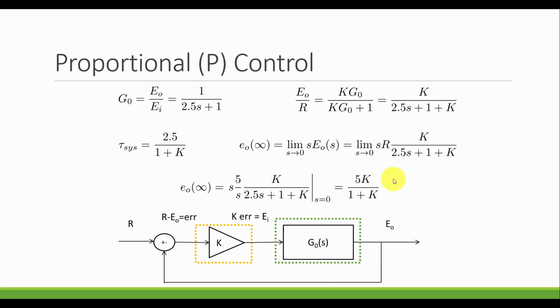I can get close, or I can get closer and closer, but it's going to require a higher and higher gain to do so. In general, when we see a steady state value like this with a K with gains in it, that's probably not a good controller. We'll address that in the next subsection, but we'll see in simulation what this translates to.